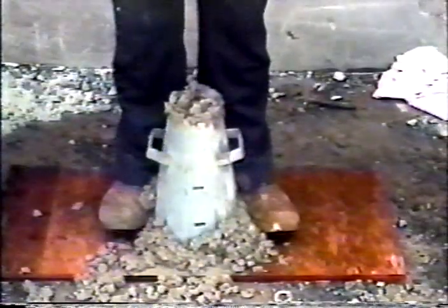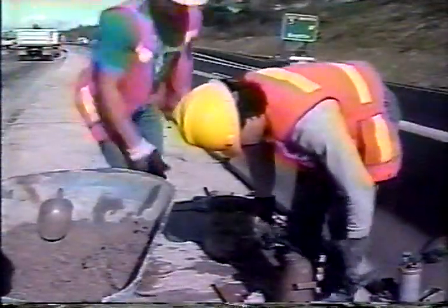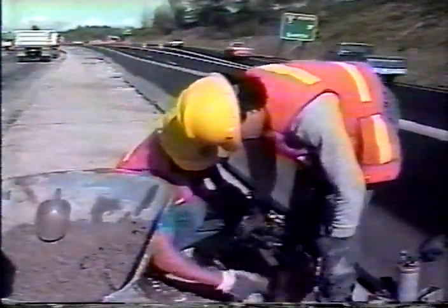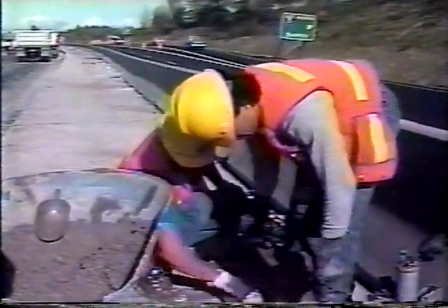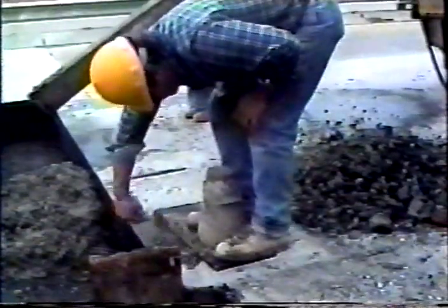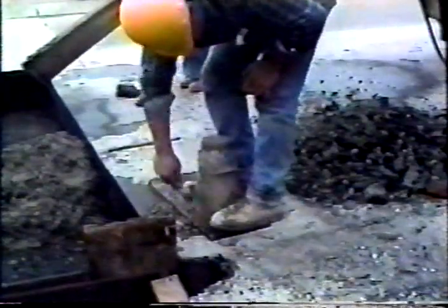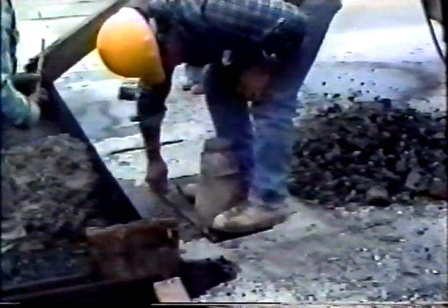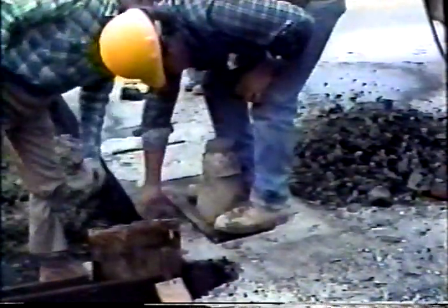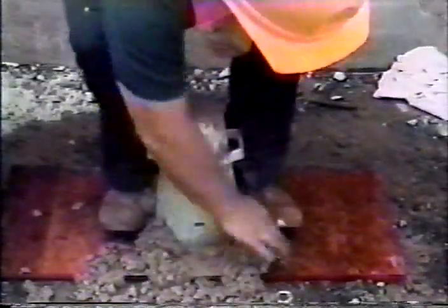With the cone full and the rodding completed, the surface of the concrete is struck off by moving the tamping rod across it in a screeding and rolling motion. The concrete surface must be level and fairly smooth. Next, any concrete that has spilled around the bottom of the cone must be removed. Otherwise, it may keep the sample from slumping properly when the cone is lifted off. However, the technician must be careful not to move the cone and disturb the concrete.